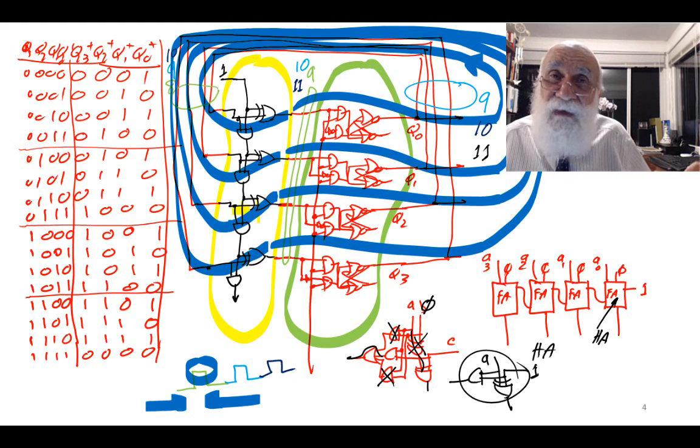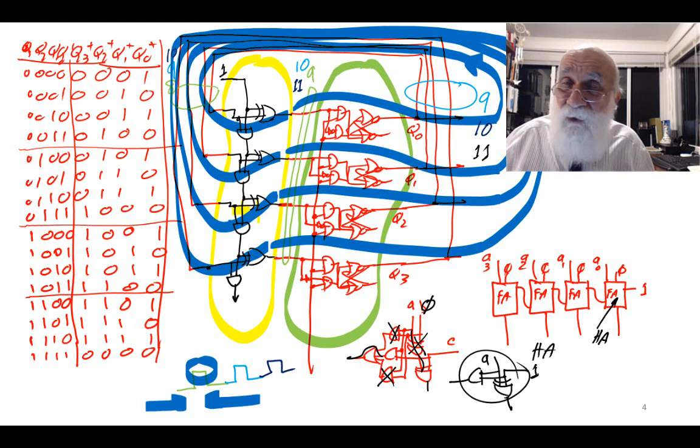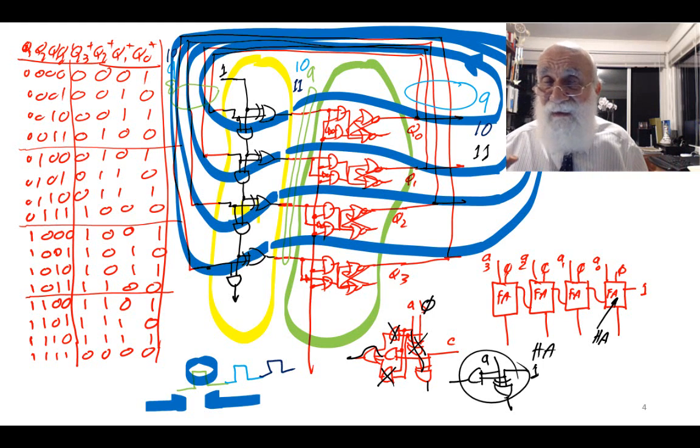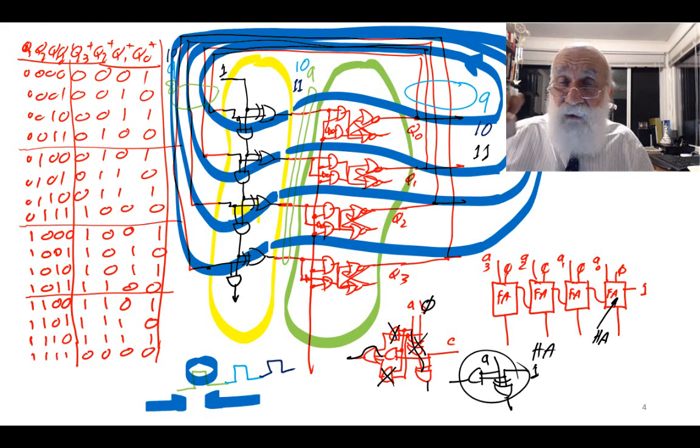The problem with that is maybe I started my circuit and the gates are not warm yet, so they have some kind of delay. And I adjust my clock according to that delay. But then later on, the circuit warms up and then the delay of the circuit is less. And therefore, I get 2 propagations, 3 propagations. Actually, I cannot design a circuit like that. I cannot design a circuit and adjust the clock according to the room temperature or the heat of the circuit or the length of the wires or the capacitance of the wires. This circuit will never work.